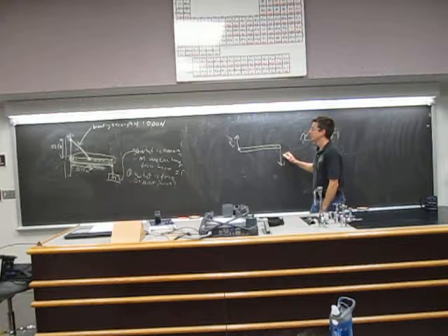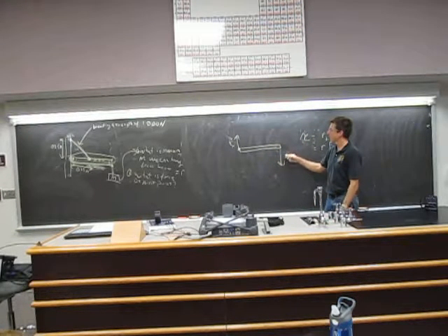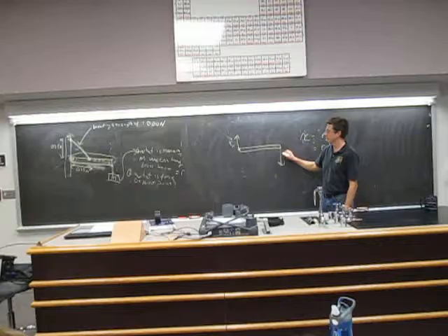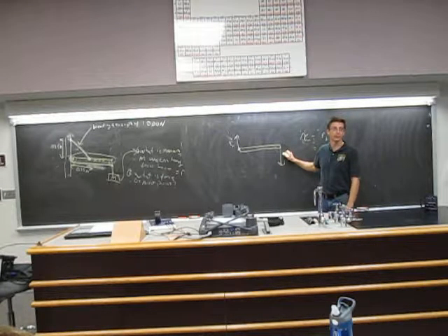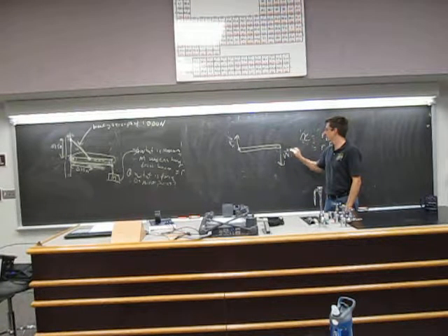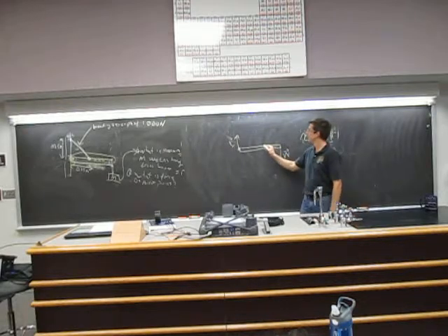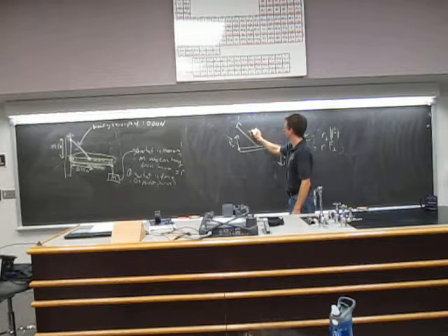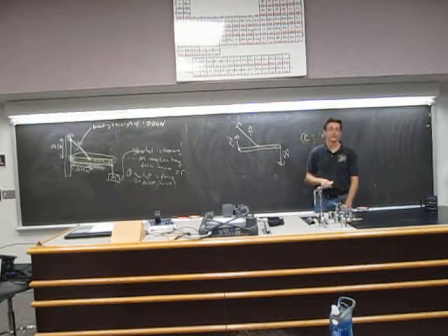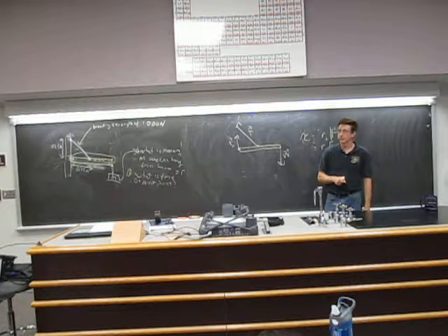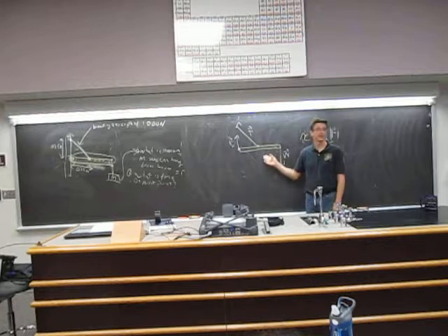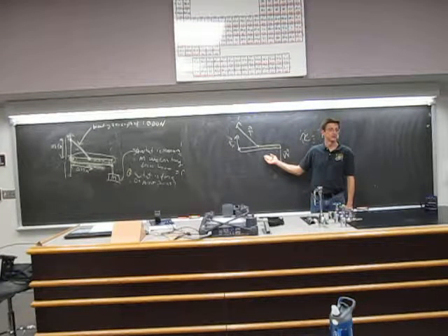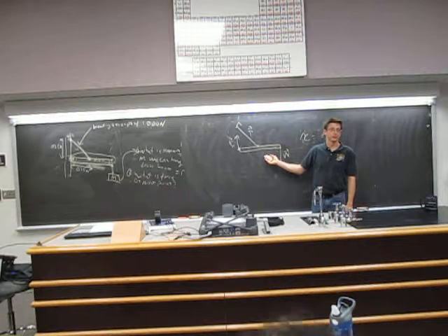I have a tension force due to that hanging mass, and I know that force is going to be the weight of the mass. I'm just going to call that weight. And then I have a tension force that's going off at a 45-degree angle on the way up. And that's it. Those are the forces, right? Provided the boom is very lightweight.